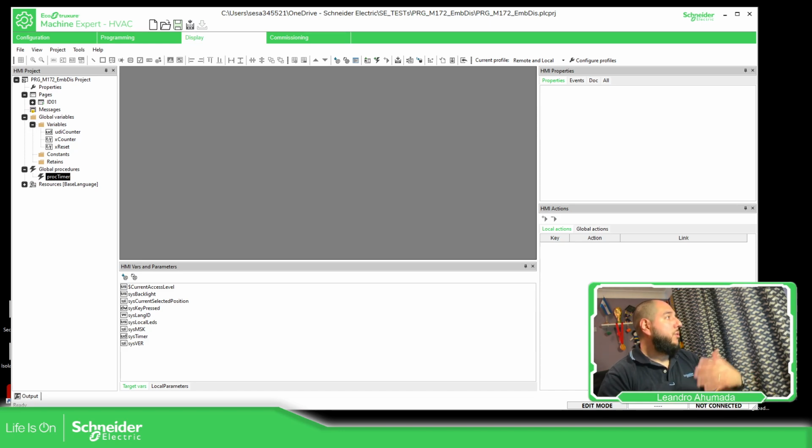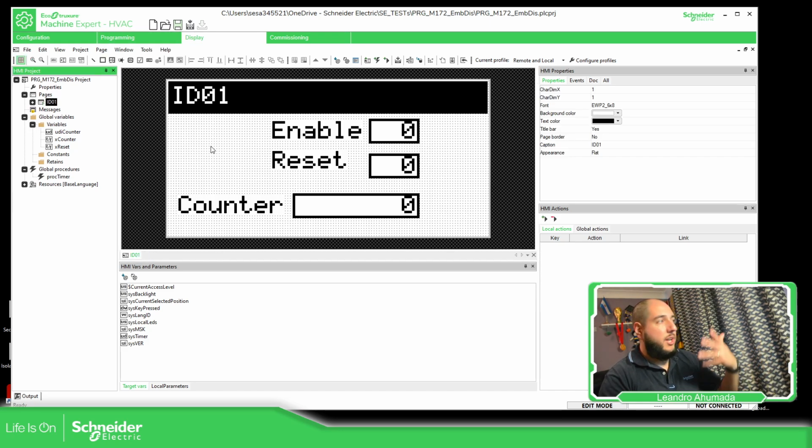Once you have already created your application, in my case I have this. If you followed the previous video about global on timer, then you know how I get to this. But right now we're going to show you the simulation. We have the possibility to simulate, to create an instance of a virtual PLC M172. On that virtual M172, we can download the code, which can be our application on the logic part of the software, which is the programming, and we can also download the display. We can download both, or one or the other.